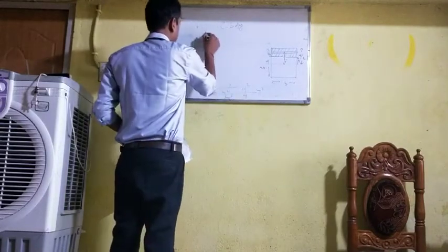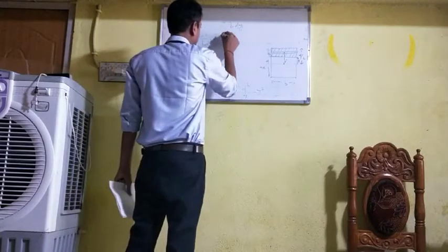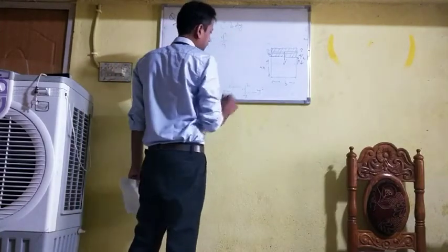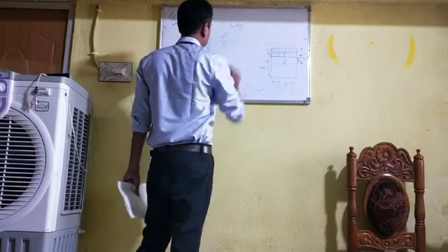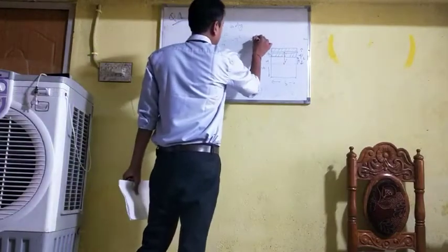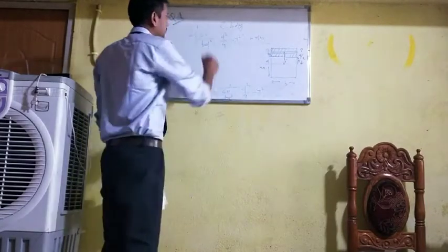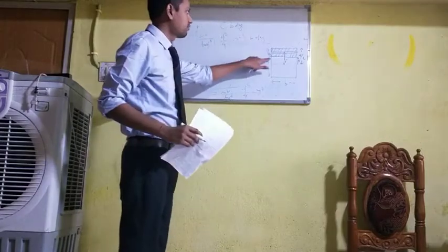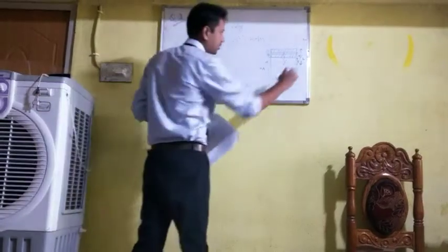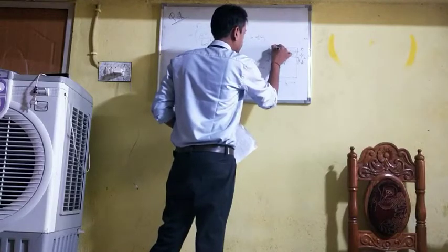Okay, this is dy. So tau, we have to put the value of tau here. Tau will be 6V upon BD cube, d square upon 4 minus y square into b into dy. And we have to integrate it from this portion to this portion. As it is d by 2, this is d by 6 and this is d by 2.